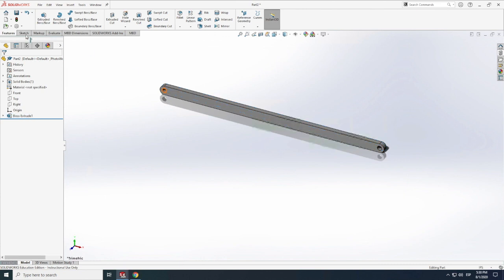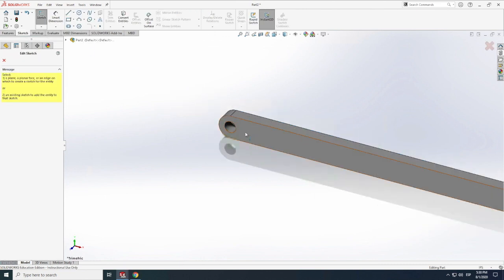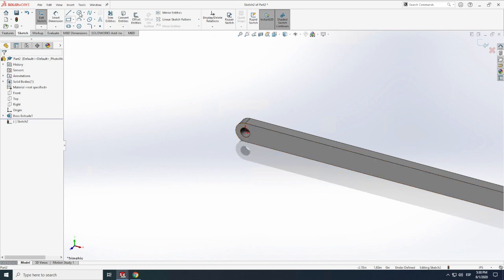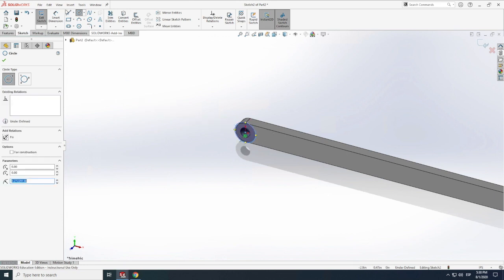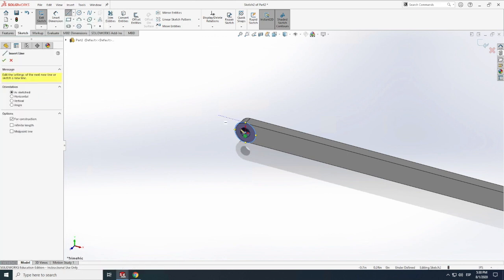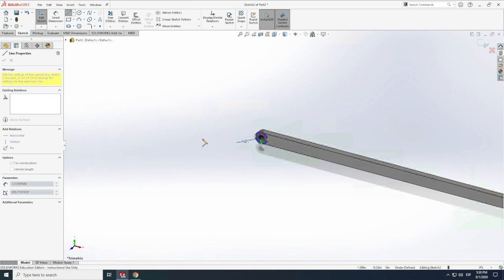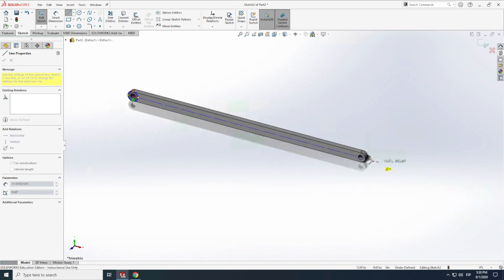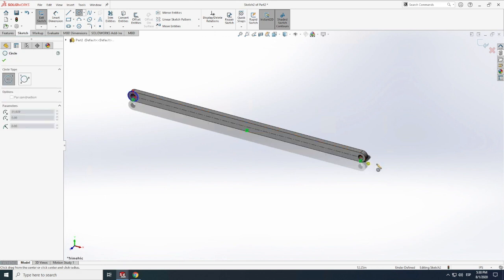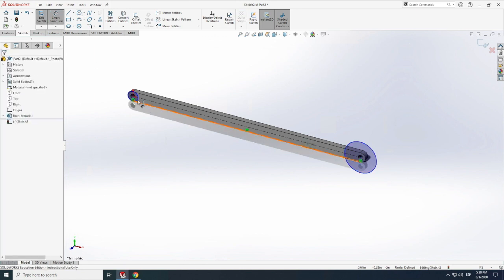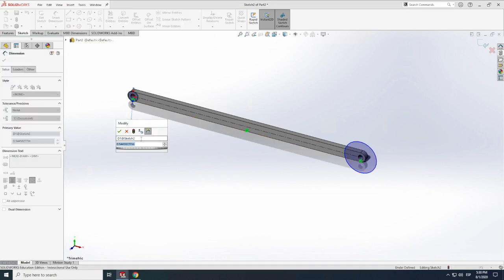And then we're gonna do a sketch in here. Here's what we can do. We can do a circle that goes all the way to the, well, we'll do a circle there. And then just do another center line that goes all the way up to that center. So as you can see, the length of that line is exactly what we want. We'll make our circles there again. Let's define them to be 1/4 inch.